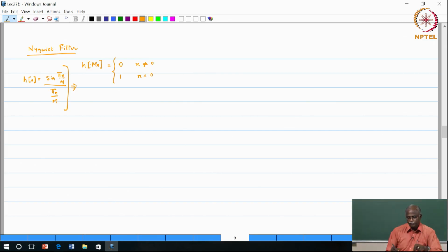Okay, so basically from the expression of the sinc function, what we found was that only one non-zero sample was there for one of the polyphase components. So this is something that we leveraged. So this basically said that if I took the polyphase component E naught of z to the power m, that as 1, then we have the following property of an mth band filter.